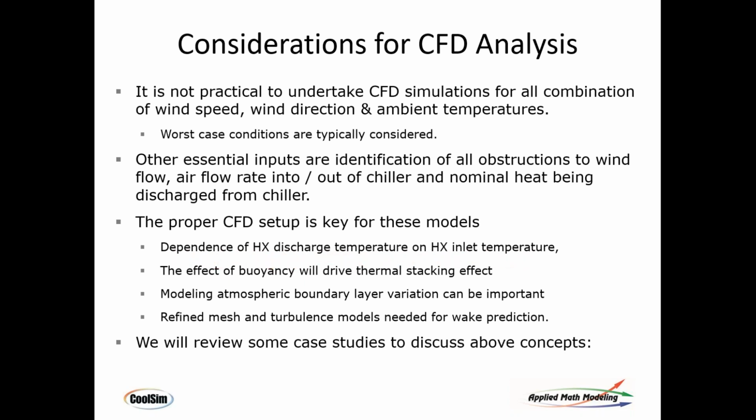That's how they work. You also have to take into effect buoyancy. Buoyancy is an important element to take into account. Buoyancy is essentially hot air rising due to change in density. That will cause its own stack effect where you'll have thermal conditions and velocities that will occur based on change in temperature alone. Much the way a hot air balloon floats is that same kind of idea.